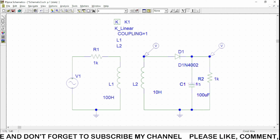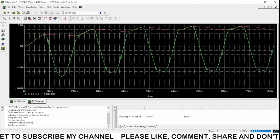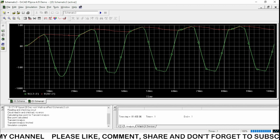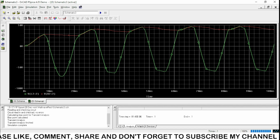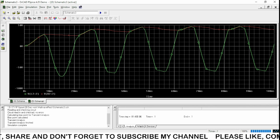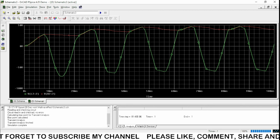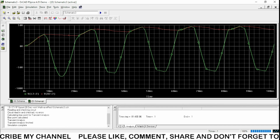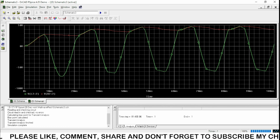So we'll again fit to page, analysis and similar. So you can see now the voltage. I've said that the very first cycle has a very low value actually, and the very next cycle will have a value from 0 to 50. So the capacitor will charge, it will discharge very slowly, it will charge, it will discharge very slowly, and so on. So from 60 millisecond, or we can say from 40 millisecond onward, you will see that the voltage is between 40 to 50. It is varying between 40 to 50.